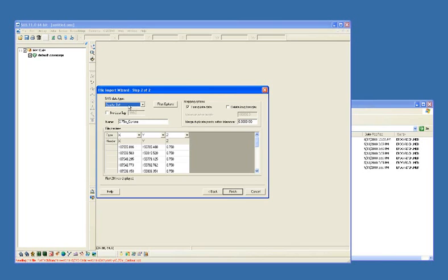We have a scatter set is what information we're bringing in. We can give it a certain name so that when it appears in the data tree, this is the name for that. You see here is the header that I specified, and it always assumes that the first column is X, the second column is Y, and the third column is Z. It has nothing to do with the values that are on this header line. It just happens that they're identical, but that's not necessarily the case.